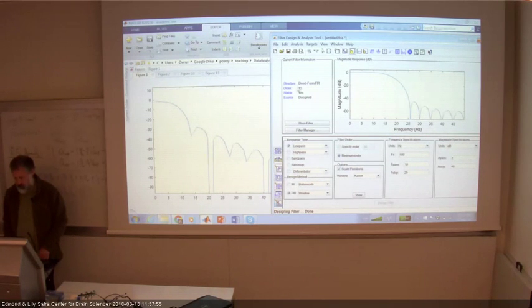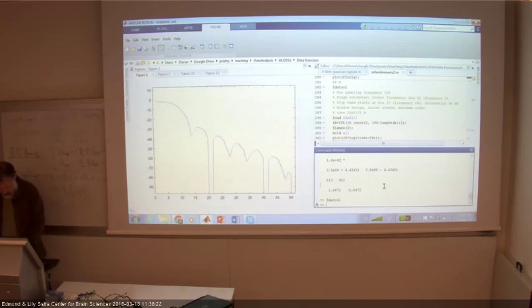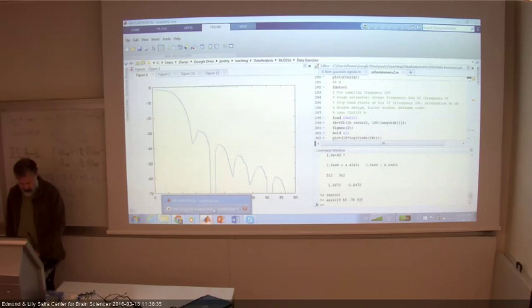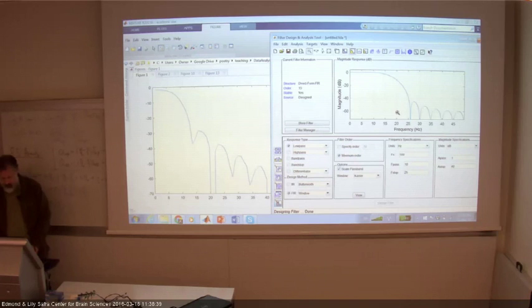Now, the question is whether this is really what I want. So let's plot this. I set the Y scale here and here to be the same. So in a way, you can see that the filter here is too good. It has a relatively narrow transition band, and it increased a lot the pass band. The effective 6 dB point is not 10, it's something like 16.